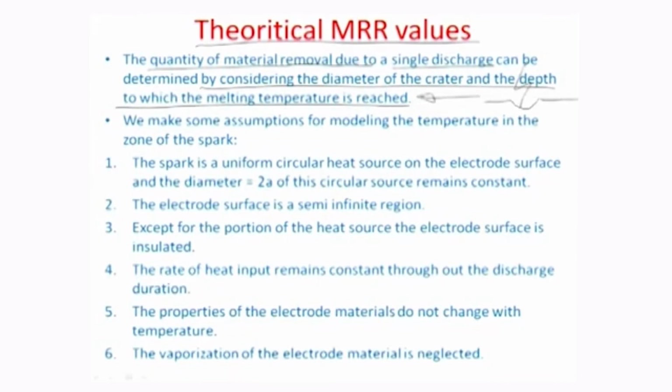because of an arc which comes and strikes the surface, we really need to estimate what is the zone which gets affected from the surface, and this zone which gets affected really is the zone where the melting would happen. So this mass right here is actually a melt pool, okay, and we call this depth d the depth of melting temperature.